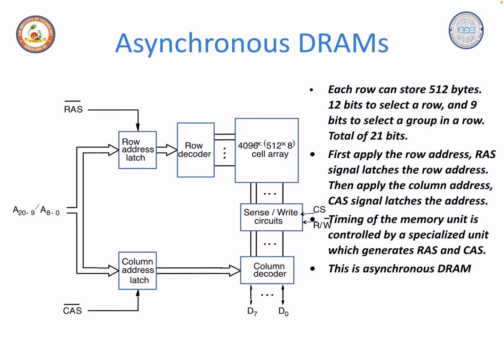So totally they are dividing the 16 megabit DRAM cell into 2 mega cross 8. That 2 mega again they can divide into 4K cross 4K. That 4K again they can divide into 512 cross 8 cross 4K. So that 4K cross 512 is the address, and that 8 is the data lines.